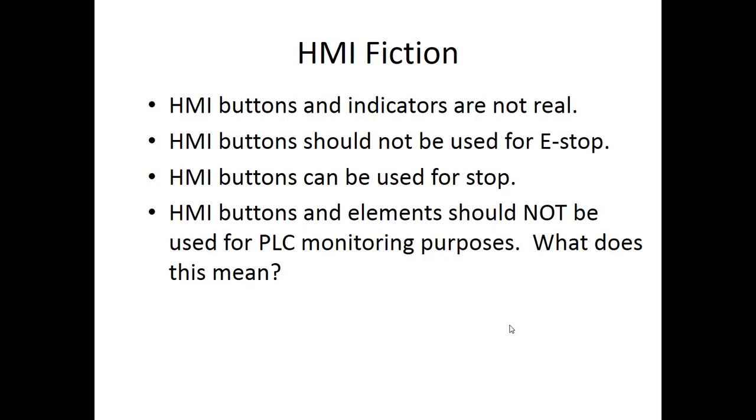Therefore, HMI buttons should not be used for an e-stop, because if the screen gets broken or somebody steals the HMI or something like that, that's not the same as an actual e-stop getting damaged or being pushed or being removed from the system. An actual e-stop is a hardwired device that's going to bring the system down and kill it. Because HMI is fictional, it's not going to work like that. So HMI should not be used for e-stop. HMI buttons can be used for a stop, but just not an e-stop.